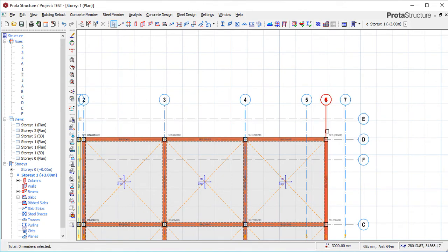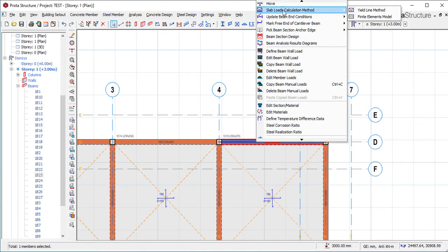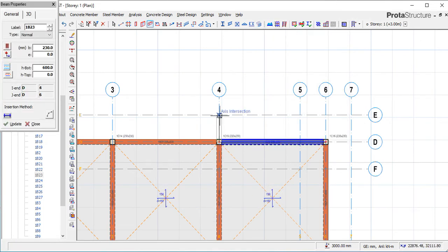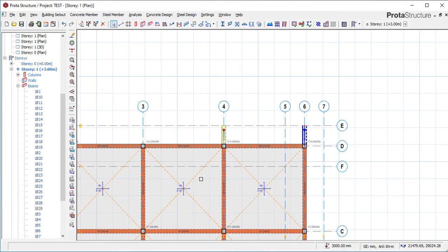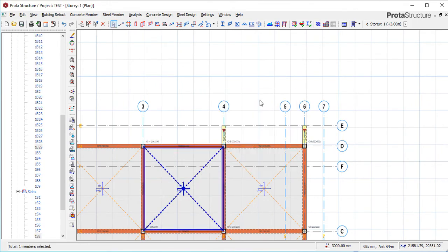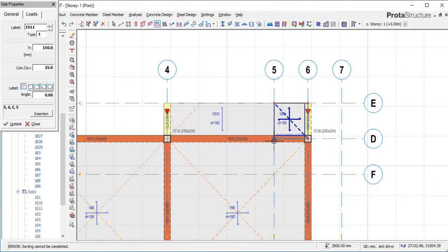So what you do here is two ways, like what I said. We are trying to create our cantilever now. We can either say, okay, let's create a beam. By creating a beam here, you can now put your slab on it. But please pay attention. If you do this, this is what you will get as your slab. It sees this as a two-way slab being supported by a one-way slab, which will result in failure.